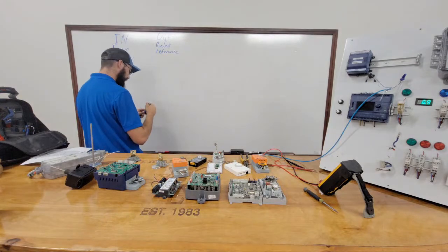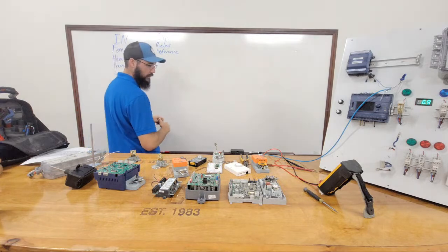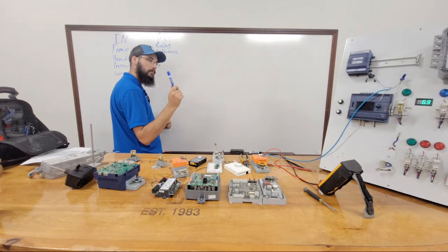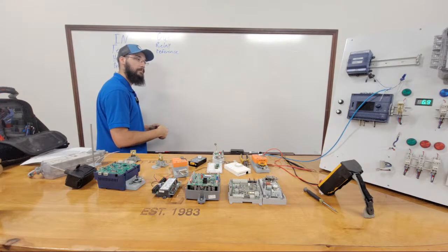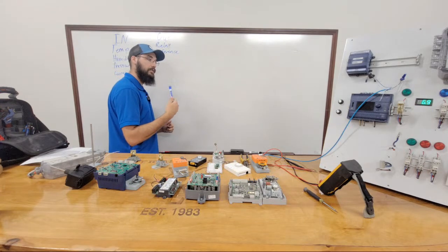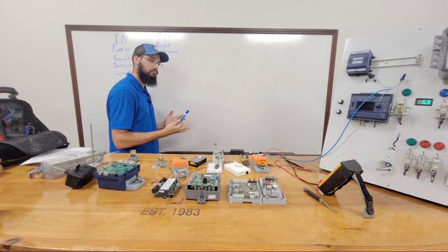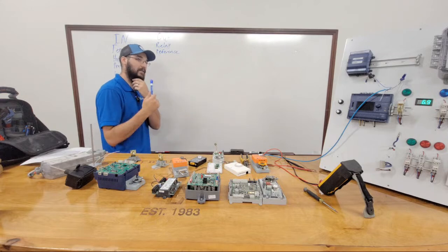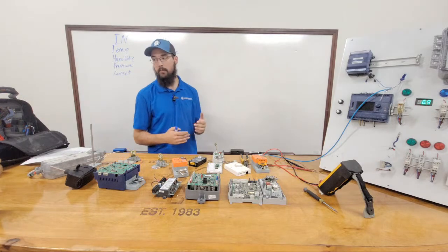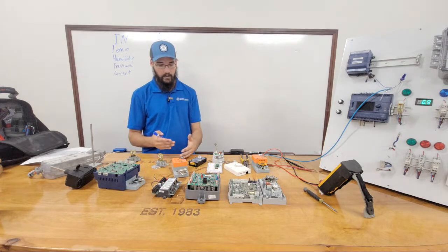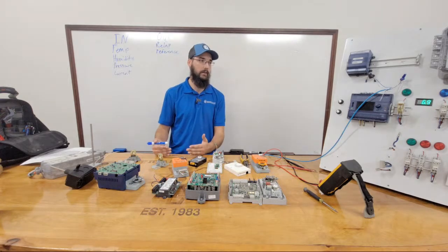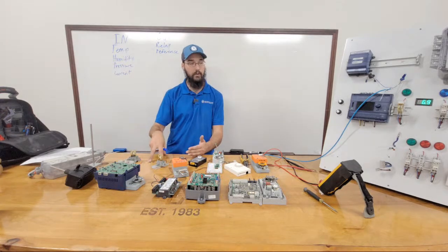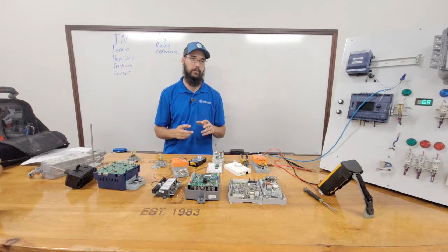So reference, when I say reference, that can mean multiple things. It's kind of a broad term. But I want to be very specific with using that term because a lot of devices, I'm seeing manufacturers use that more and more consistently, especially when you start dealing with VFDs. So a lot of VFDs, you have a reference point coming into it. That reference is your input signal. That's your speed signal, if you will.